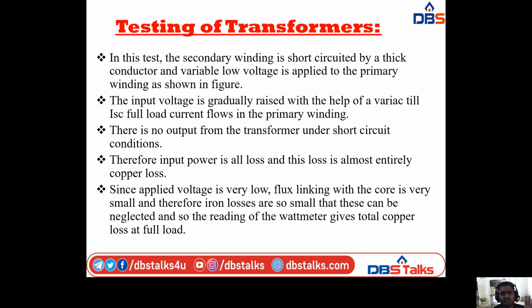The input voltage is gradually raised with the help of a variac, up to the point where we get the short circuit current I1 flowing in the primary winding.